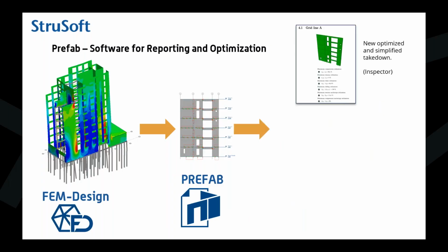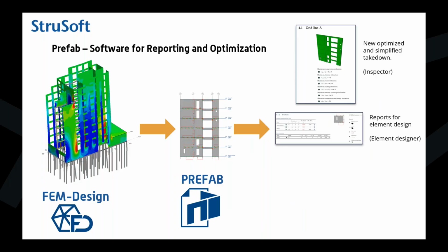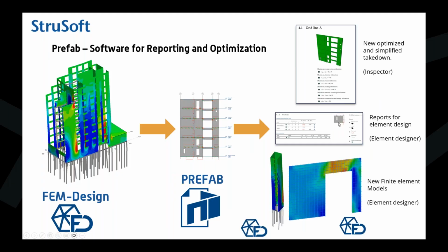But we will look at examples, and what it spits out is the total new load takedown with the optimization. It also gives you an element report. So if you want to give some paper to the element designer, this will give you the loading to the certain element and the grade of element, size of the opening. So you can design the whole element and calculate it with this data. And the third thing it can do, it can generate totally new finite element models out of the original model.